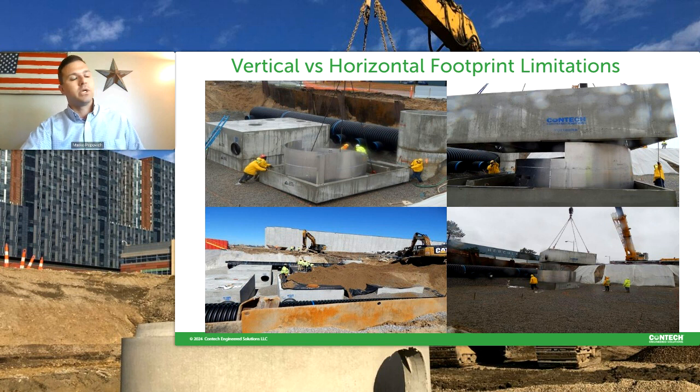And ultimately, I did see some questions earlier around the internal components themselves, and are those actually set, or is it expected to be installed in the field there? For this one, that aluminum swirl chamber on the top left-hand side and really on the top right-hand side as well, that came separately. We shipped out the base section, we shipped out the top section, and then we shipped out the aluminum, the hardware, the sealant, everything to actually connect that swirl chamber into the vault.